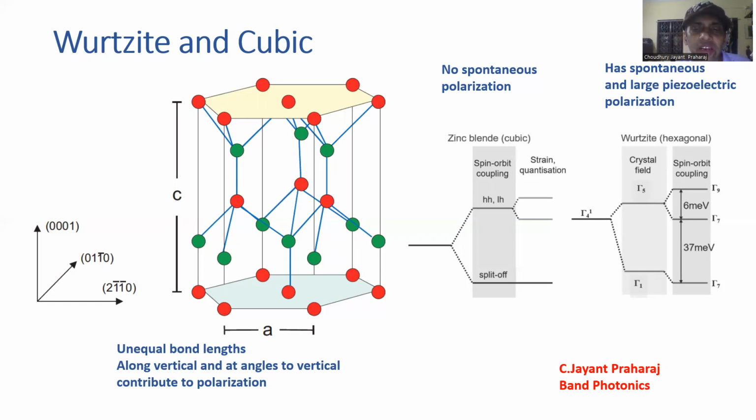So we have this material grading. So material grading also gives rise to spontaneous and piezoelectric polarization grading in these materials. And polarization grading affects band bending and device equations and the overall current voltage characteristics in these devices. And that needs to be kept in mind while optimizing solar cells.